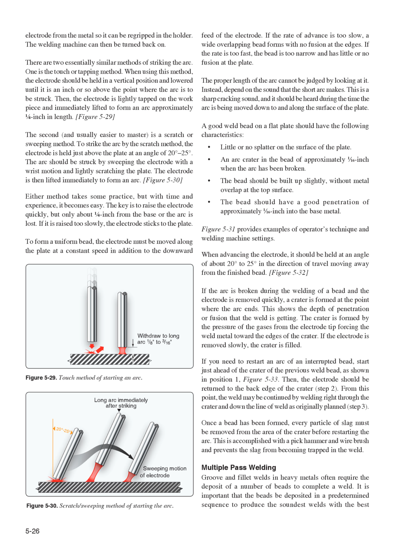The proper length of the arc cannot be judged by looking at it. Instead, depend on the sound that the short arc makes. This is a sharp cracking sound, and it should be heard during the time the arc is being moved down to and along the surface of the plate.